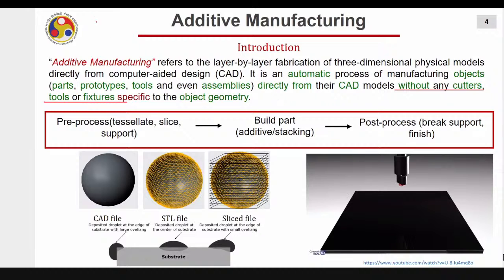I usually take an example here. For example, you want to make a cylindrical object which has a hole. It is a cylindrical object of metal, and this hole is 6 mm diameter. Now, to make this part, you will preferably go to a lathe operation, and you need a 3-jaw chuck, right? And a 3-jaw chuck is good enough to hold this particular object,